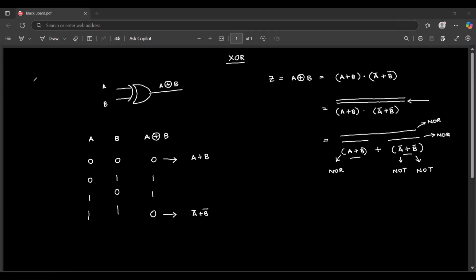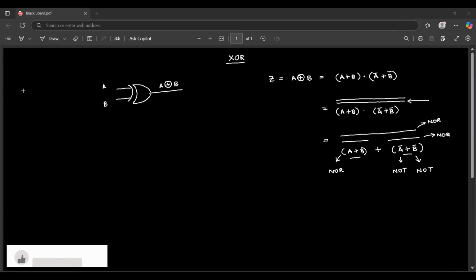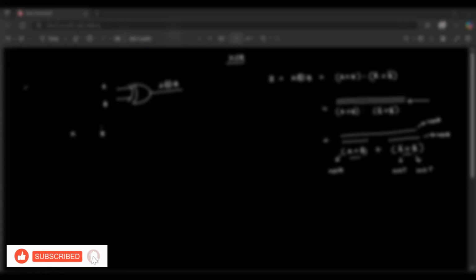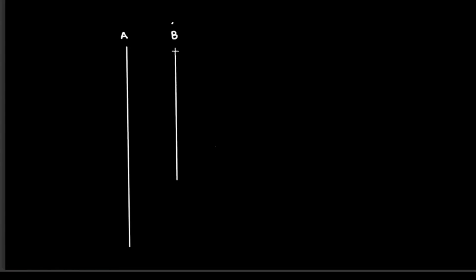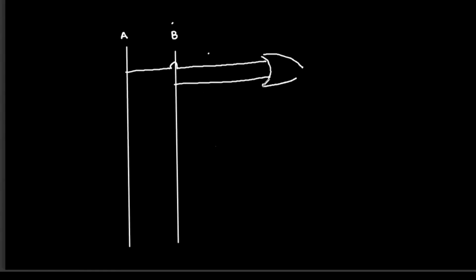Now you can come up with the logic circuit by using NOR gates easily, if you have this foundation. So let's have A and B, and then the signal lines. I really don't know what these mean, but I just call them signal lines. First of all, A plus B whole thing bar is not an issue, because that's a NOR gate. So we can directly use a NOR gate without any issues. So here we have A plus B whole thing bar.